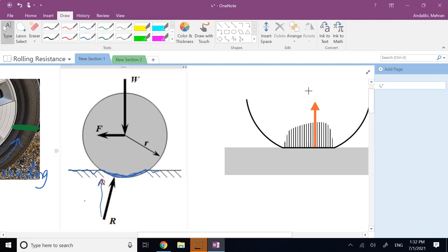A vertical component, N, that you always know, and that will cancel your weight, and it has this X component, Rx, which is the same as what for us? That rolling force. So let me call it just F of the rolling resistance. And this one is clearly acting opposite to the direction of motion and is wasting energy.